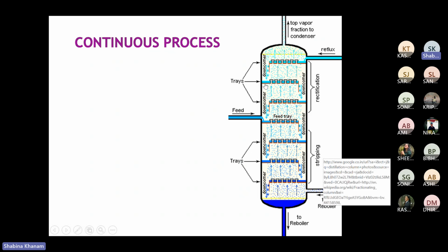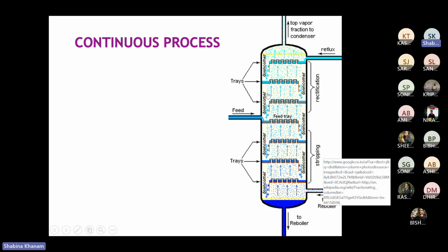If you can see, holes are not available in this particular section, or this section, or this section. The point to consider is that wherever the liquid falls from the top plate to the lower plate, it will first stay over this section where holes are not available, so there is no possibility for liquid to move down.